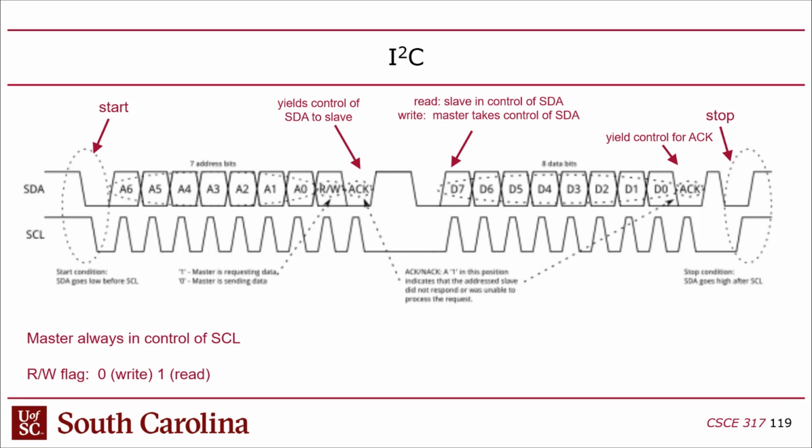Now you might say, what's the advantage? I thought latches are always inferior to flip-flops. Well, in this case, I think latches are good because you guarantee that the data is stable while the clock is high. That's the reason why latches have a bad reputation: it's tough to guarantee that nothing will change when the clock is enabled. But in this case, SPI is designed specifically to keep the data stable when the clock is high, so I think they basically just use latches.